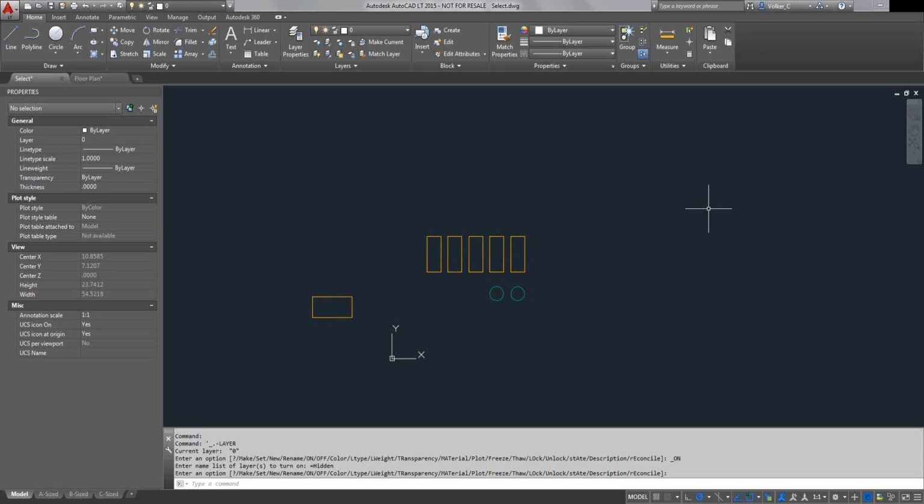The only reason it's not selecting the stuff on the frozen layer is because basically AutoCAD locks that in the database and pretends it doesn't exist. So when you're selecting all, it ignores that. So be aware of that with select all. Otherwise, a very cool tool to select everything and then shift to deselect the stuff you don't want to modify.